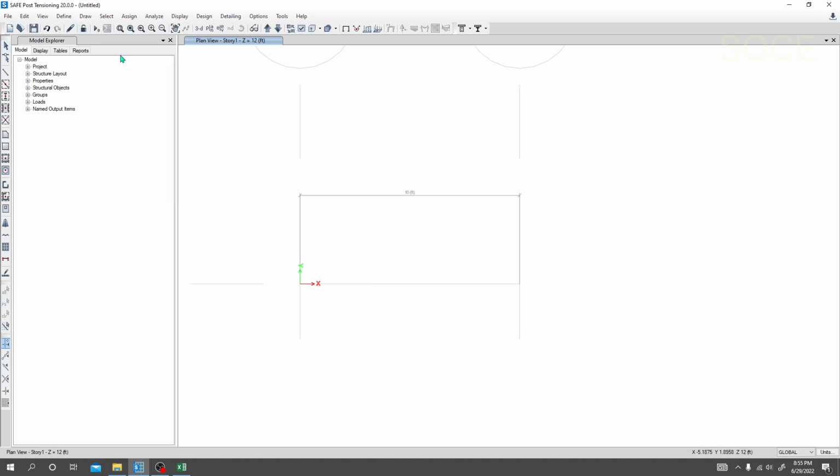So click here, draw joint object, and from here I'll draw our joint. In the y direction I'll take 2 feet, or 2.5 feet, so it is 30 inch in the y direction for a point, and in the opposite x direction, what will be that value?